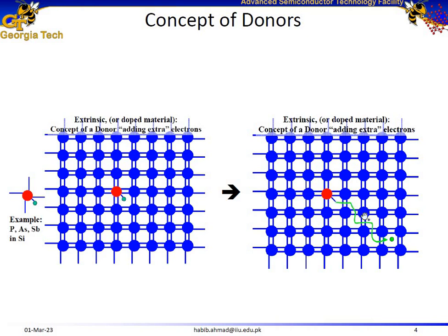And when it releases that electron into the crystal, this electron can now easily move around in the crystal, but it releases an electron, so it's going to introduce a positive charge on the phosphorus atom inside the crystal lattice. So basically, the introduction of donors, after releasing the electrons, introduces positive fixed charges inside the crystal lattice.